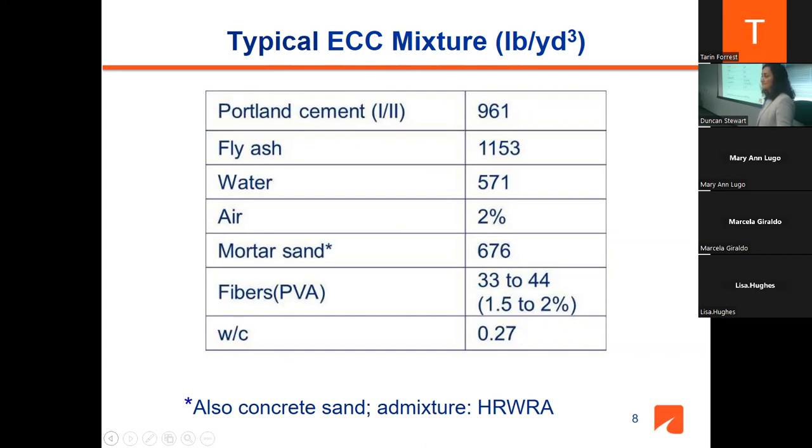And one other thing we are doing at VDOT is trying to use maximum total cementitious materials, not minimums. Like our low shrinkage bridge deck concrete has a maximum cementitious material of 600. So that is another thing, pushing people to use lower cementitious materials, especially Portland cement, which is one of the highest carbon contributing materials. But when you look at concrete, it is one of the better materials in terms of carbon footprint. So that's the sustainability.